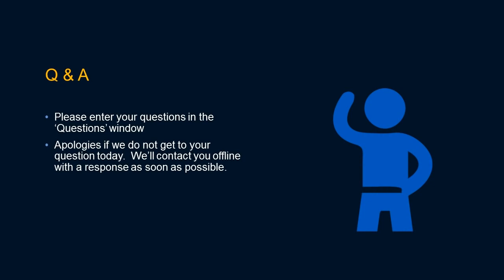Modbus Plus is a Schneider Electric protocol, but one of the big advantages of regular Modbus is that it's open source, that everybody knows how it works. Modbus Plus is a proprietary protocol that they manage. And it even functions differently in terms of how the networks work. It's not a master-slave protocol. It's a token-passing protocol. It's really an entirely different way of communicating between devices. So that could be its own webinar in its own right. And unfortunately, they really aren't compatible. It just happens to share a name for marketing purposes.